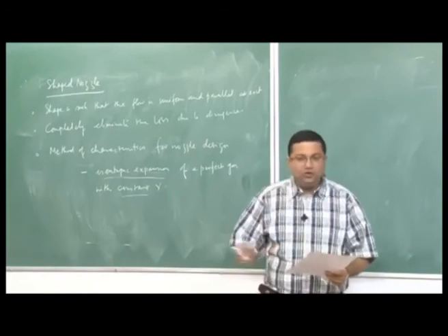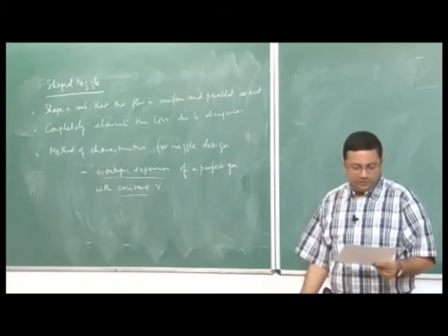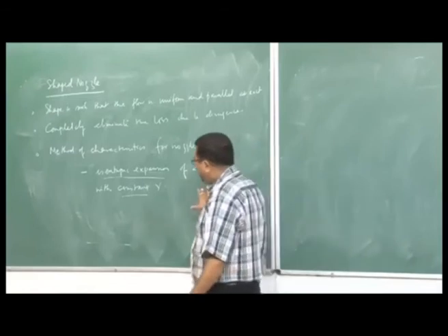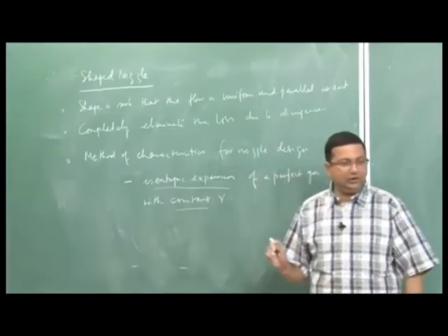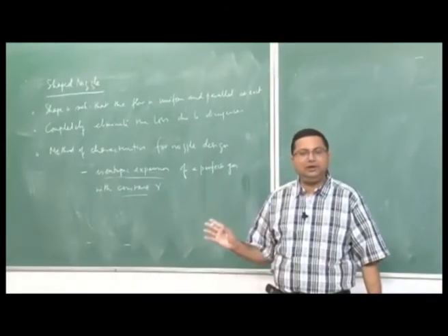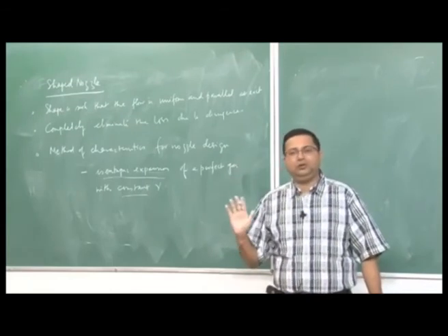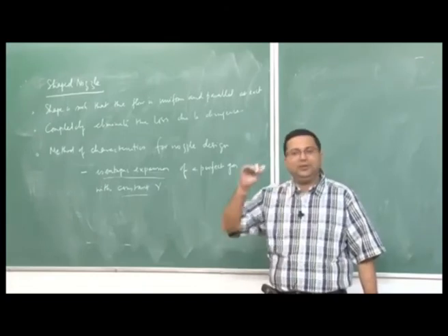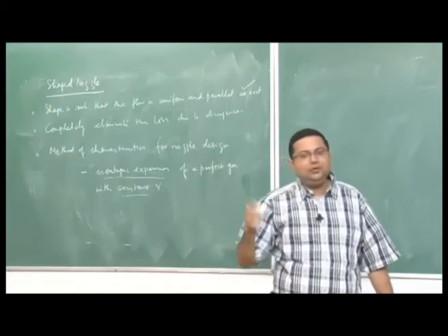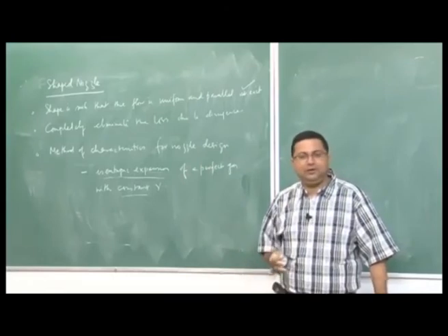It can also be used for variable gamma, and chemical reaction can also be incorporated, even the wall friction can be incorporated, that we will come to later. At present, we will consider that the value of gamma is constant, we will not consider any chemical reaction, we will not consider any wall friction, we will use the classic method of characteristics to get the contour, that is what we want to do. We want to get a basic contour that will give us this. Okay. Then after that, that basic contour can be modified by bringing in more complexities, okay. That is something not very difficult to do.